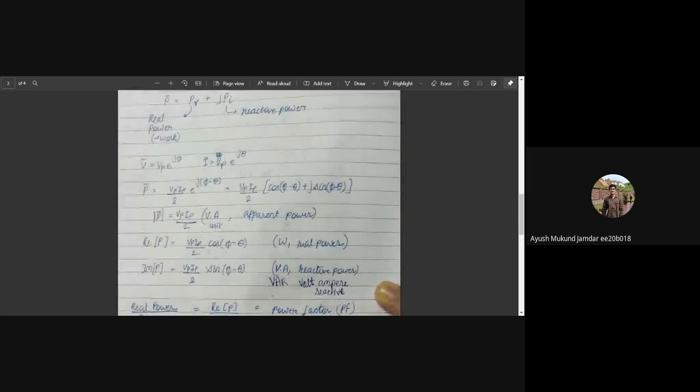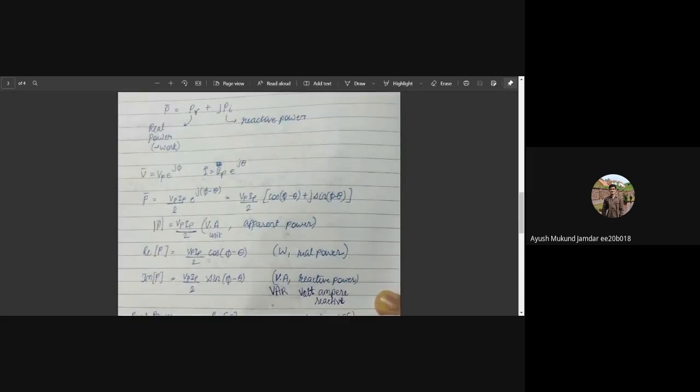Let's say R, C, and L are different circuits. You can clearly see that the average power delivered to the resistor will be V_p squared by 2R. For the capacitor and inductor, it will turn out to be a complex value, meaning that there will be no real power delivered in one time period, and so on. So continuing the same discussion, we have V bar, the phasor, let's say it turns out to be V_p times exponential j phi, and for I bar, the phasor turns out to be I_p, the peak current, times exponential j theta.